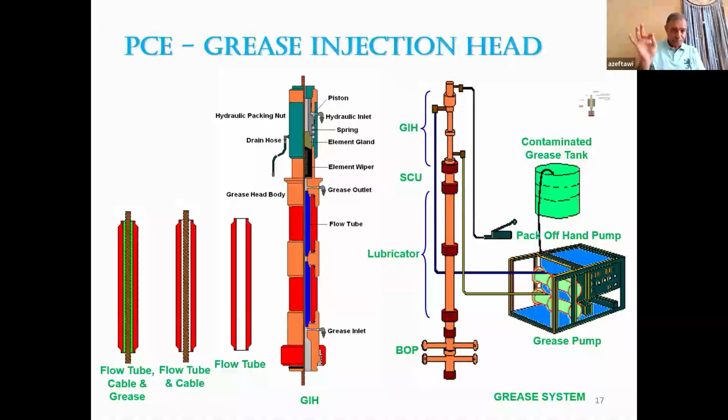with the pressure higher than the wellhead pressure by minimum 1.2. So if the wellhead pressure is 1000, they keep the circuit at least 1200 psi, preventing the well pressure from escaping out.